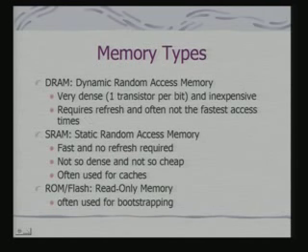Here we have a comparison of their characteristics. In fact, dynamic random access memory is very dense and consequently inexpensive. But it requires refresh. Why does it require refresh? We shall understand when we look at its structure. Static random access memory is fast. No refresh is required, but it is not as dense as dynamic random access memory. And often it is used for cache or other applications where we require really fast memory.